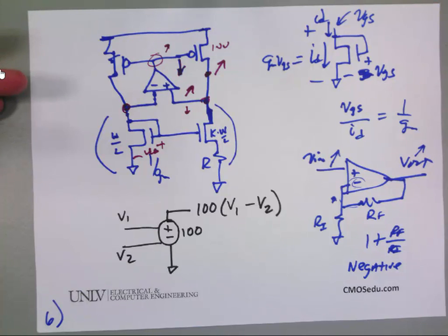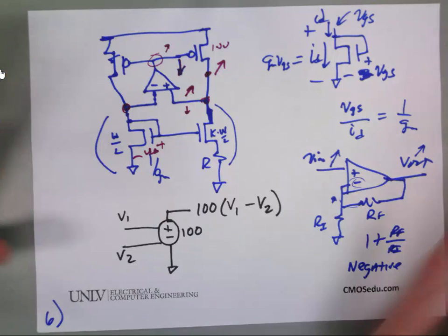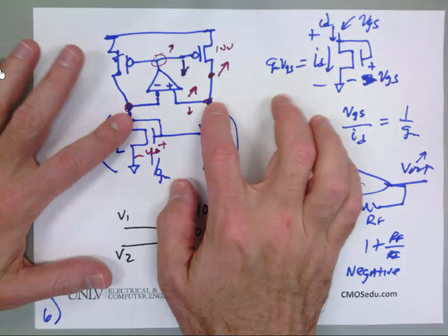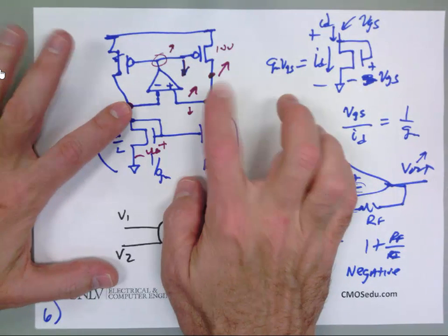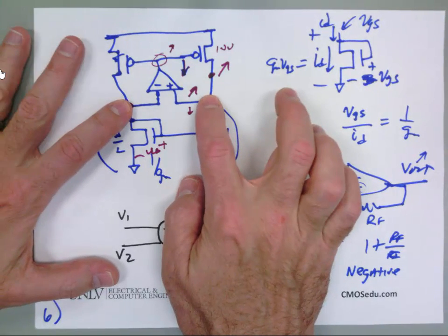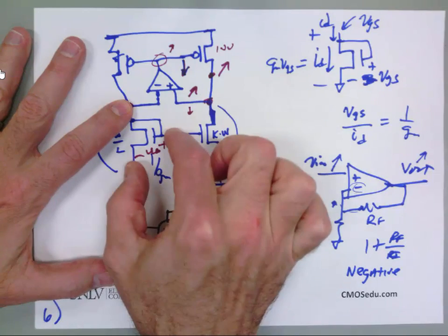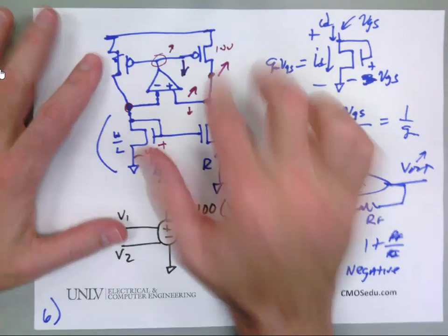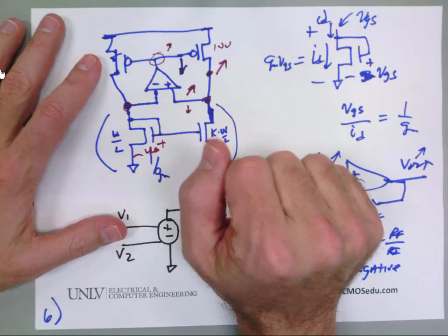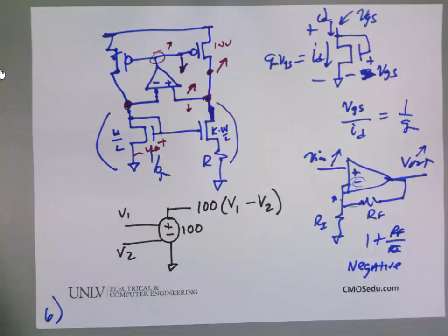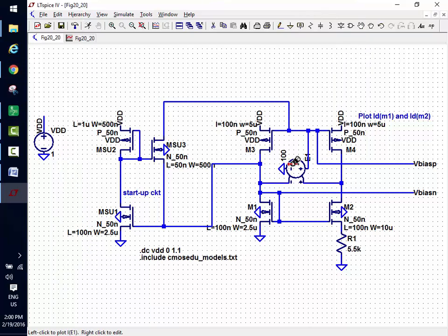So I need to have a circuit that I can use for an amplifier. Does everybody understand what I'm trying to do here? Trying to make sure these two voltages are the same, which then means they'll be VGS, so that the currents through each side don't change with changes in VDD. I just showed that that works using a voltage controlled voltage source.